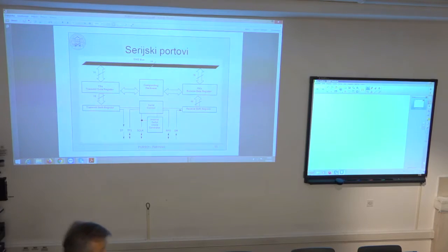And one of those that is commonly supported is I2S, or IIS. It is used for serial communication of audio data, 16-bit, 24-bit, or 32-bit, one channel, two channels, and so on. So this kind of high-quality stereo or multi-channel audio data is transmitted serially over such a serial bus.